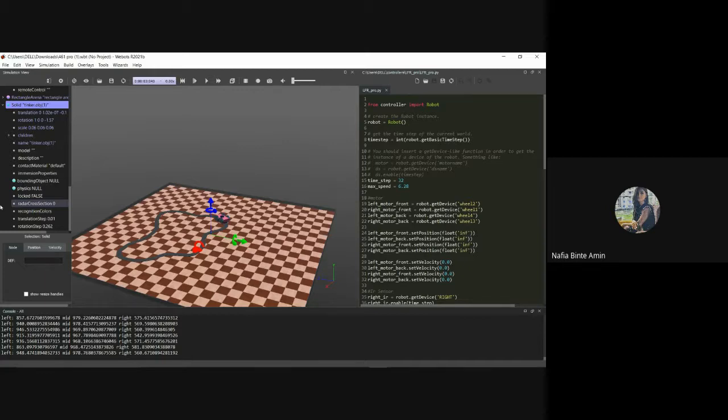From the geometry part, we fixed size, height, scaling, radius, translation, and rotation values for each shape component of the robot. We gave them PBR appearance to determine visual properties, added color separately to all the parts, applied collision by using the respective shape in the bounding object, and applied physics as well.